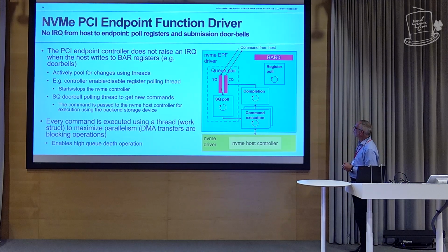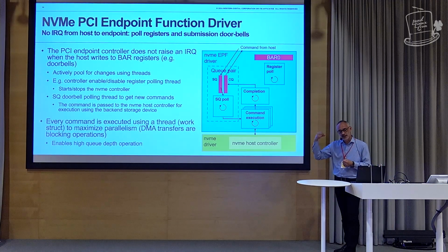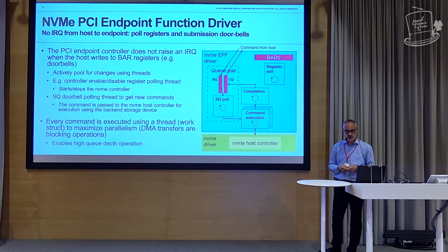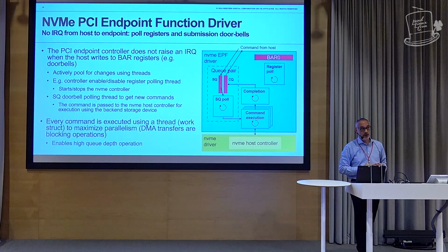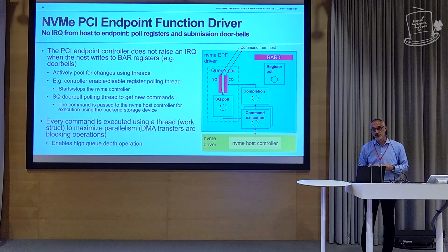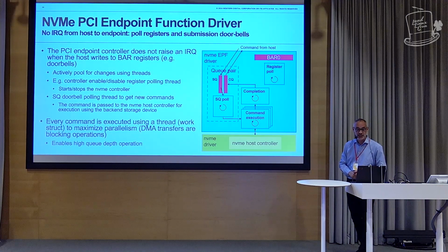There is also another thing, which is that at the initialization of the driver itself, you have to wait for the link to come up so that you can properly manage the NVMe controller state registers exposed to the host. So there is another thread that actually does polling. You also must be ready in your function driver for the host suddenly shutting down. And that is something you can detect as well by looking at the controller status registers.